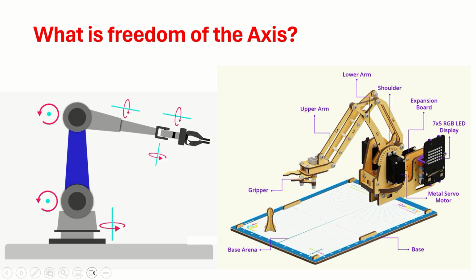The second thing is by how many degrees that rotation can take place. Is it 360 degrees, 180 degrees, or 90 degrees? And by what step? Is it a continuous rotation, or does the rotation happen in a step by step manner? These degrees of freedom can be achieved with the help of motors, joints, gears, and threaded screws.